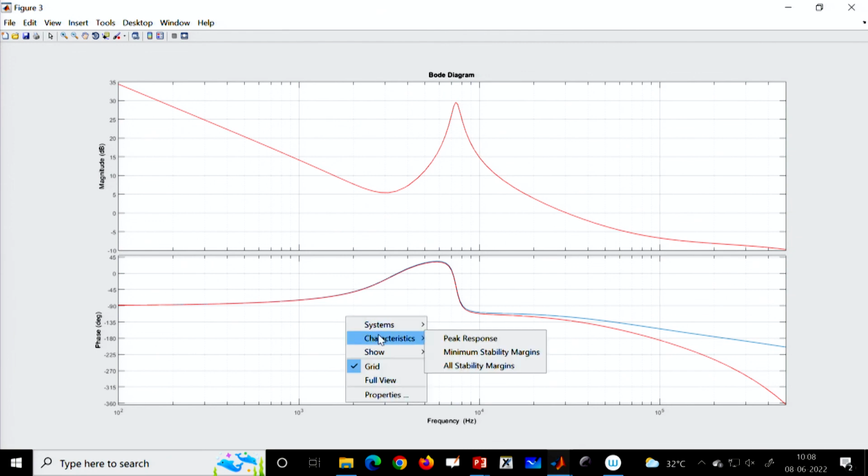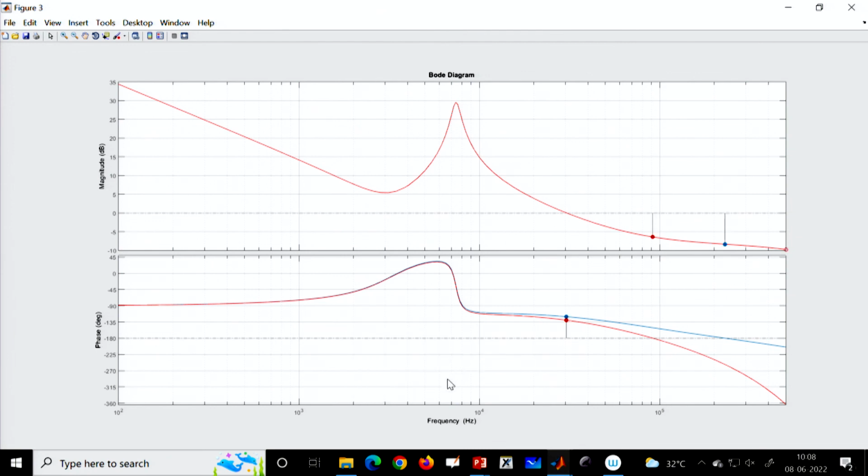Now we can get the phase characteristics. So, now we have enough phase margin. That means our derivative gain was smaller. So, we need to increase the derivative gain to get sufficient phase, and here also we got somewhat higher bandwidth. We got the bandwidth to be around 30 kilohertz compared to the earlier case, and the phase margin is now 50 degree. So, we have sufficient phase margin.